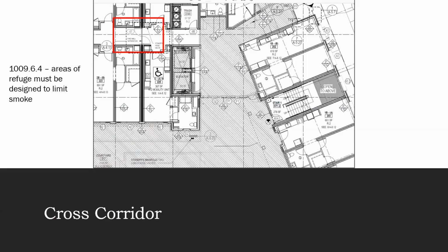So the picture here, this is a cross-corridor double egress separation. They needed both directions of travel to be available, and that's why the doors are swinging in opposite directions. Now the doors are separating two occupancies in the building, and they're pocketed into the wall, designed to be held open out of the way most of the time. But without these smoke and draft control doors, if there was smoke in one area, the smoke would easily travel through the opening and into that safe area.